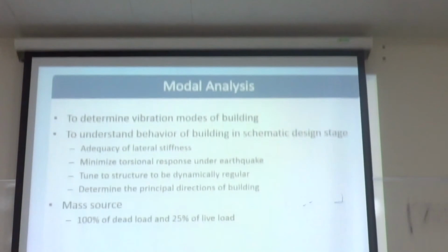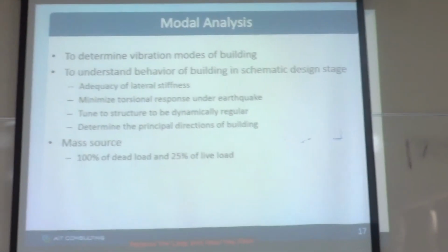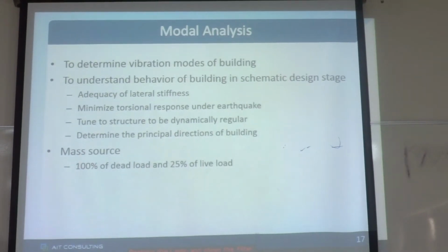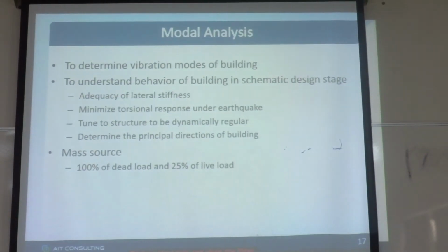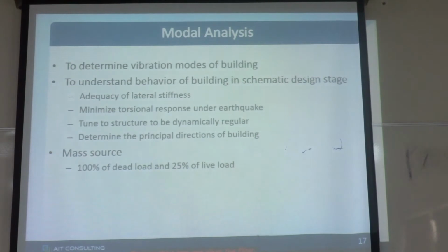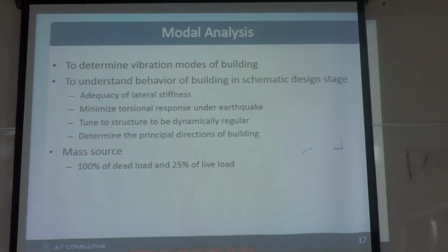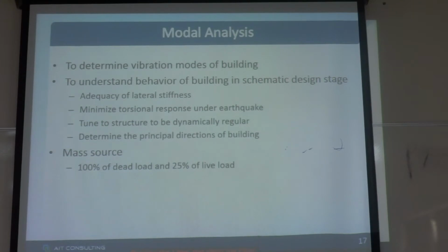Another thing is the mass source for the modal analysis and seismic analysis. We normally consider 100% of the dead load and 25% of the live load. When we do the gravity load design, we apply a live load for residential floors of 1.92 kilopascal.